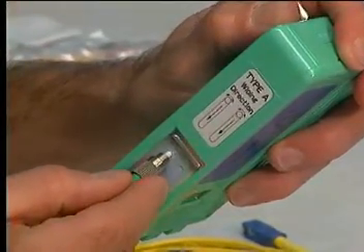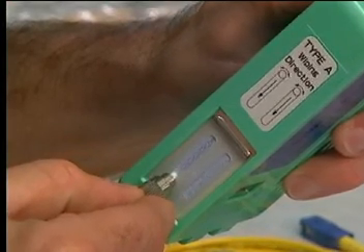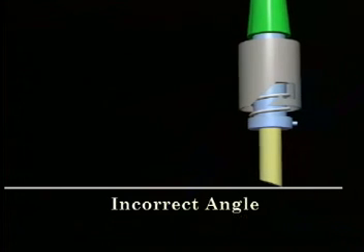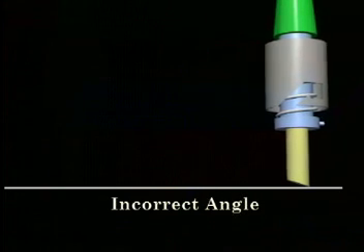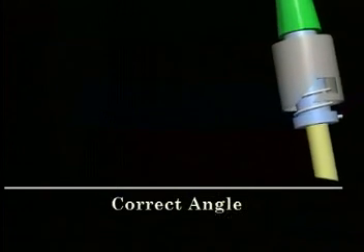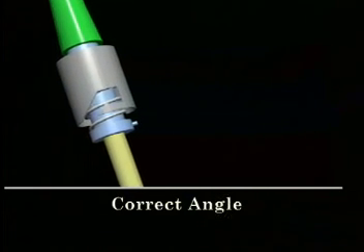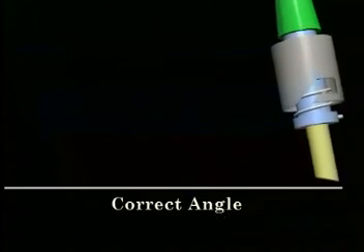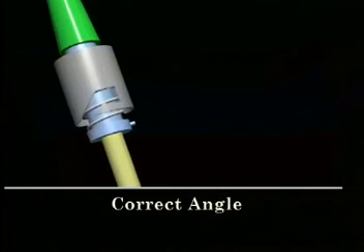With tape cleaners, you will need to initially judge the correct position by eye. Feel is also important. When improperly positioned, you will feel resistance as the ferrule edge is the only part that contacts the cleaning surface. It will feel like you are scratching the cleaner surface. When positioned at the correct angle so that the ferrule end is parallel with the cleaning surface, the feel will be smooth as the connector is moved. With practice, you will quickly develop the proper feel for cleaning angled connectors.